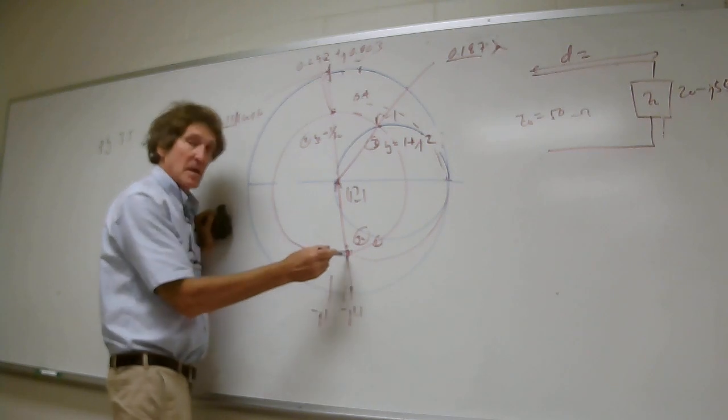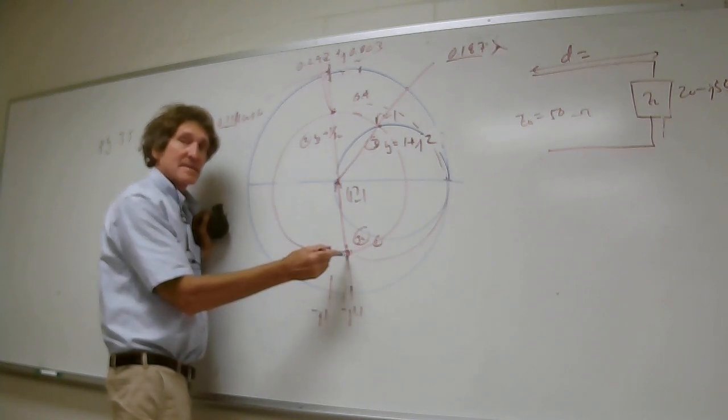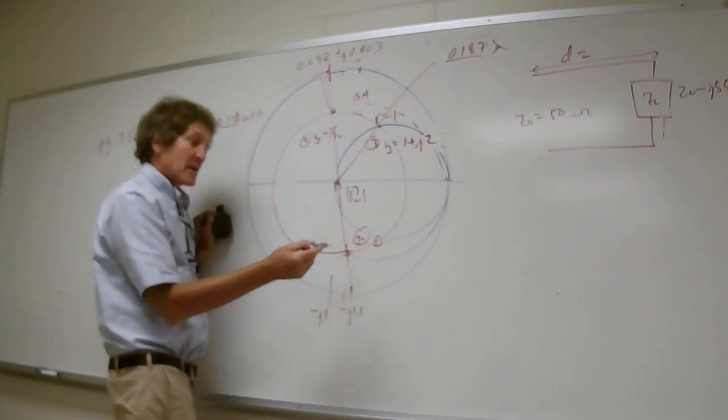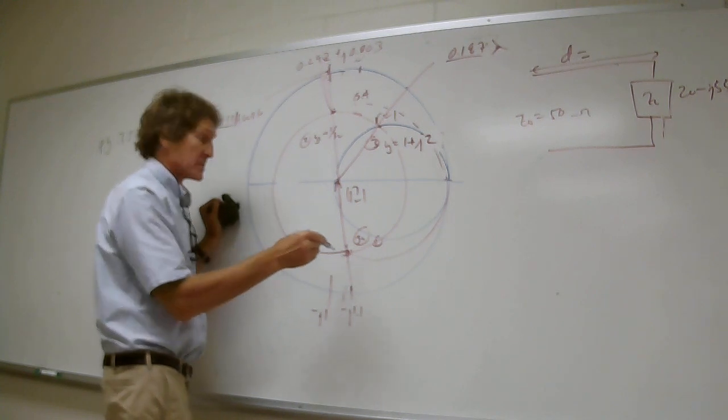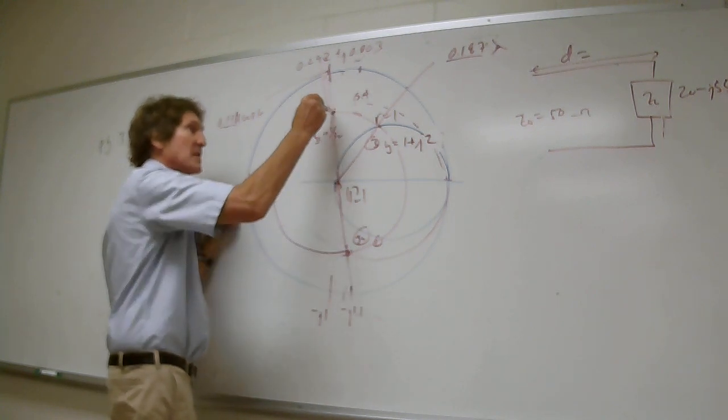You see how this is normalized ZL? We're going to connect stuff in parallel or shunt. That's the admittance domain, right? So we're not going to use impedances, we're going to get admittances. Admittances are 1 over impedances. So straight through here, this is the admittance to that point.